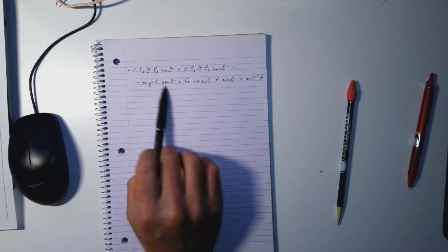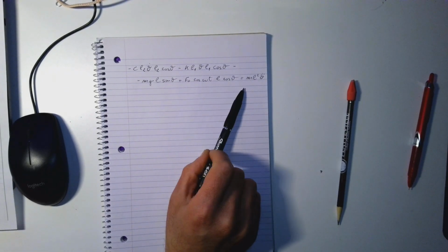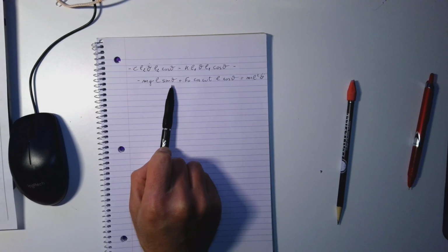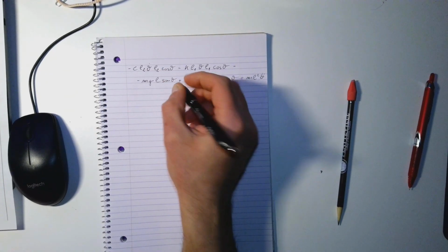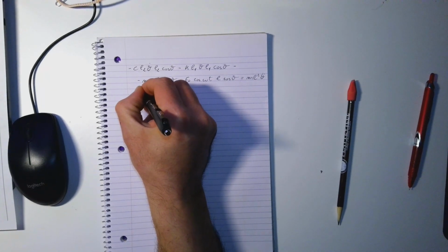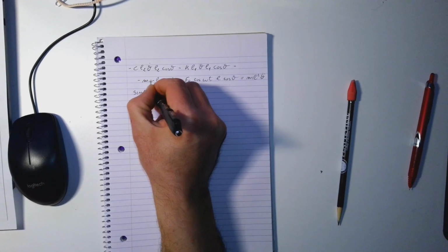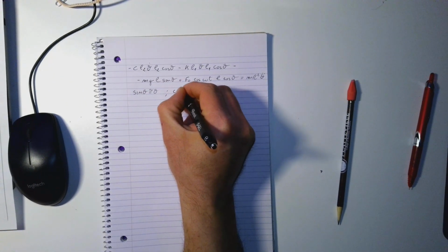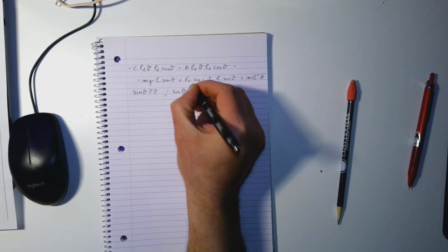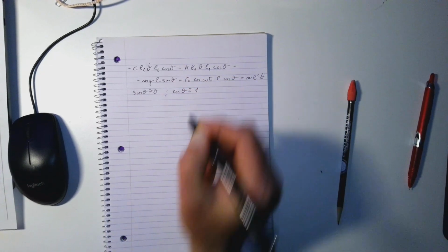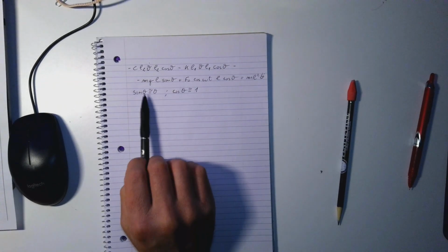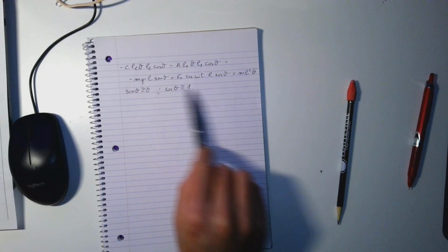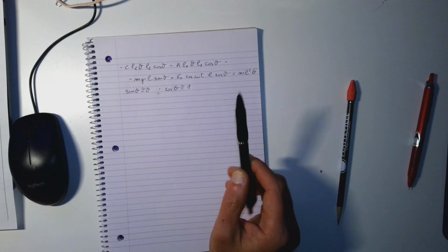So we can further simplify this one, because we said small angle, which means that sine of theta can be approximated as theta. The cosine of theta can also be approximated as 1, again because theta is small. So with these two, we can simplify, and then we can also rearrange the terms so we can get closer to our standard form.